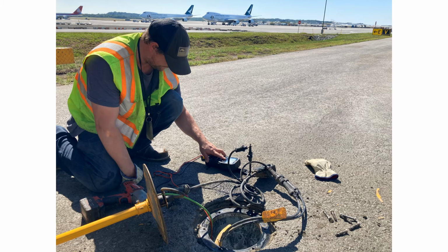Another quick way to check a transformer in the field, especially if the can you're working with has water in it, is to set the transformer up on the drive pavement and then meg the circuit through it. Then drop it back into the can full of water and meg it again. If the meg reading gets worse, then the transformer is probably bad. This only works if the transformer insulation has been breached, which is often not the case. So you can't always trust this method, but it's a quick try.